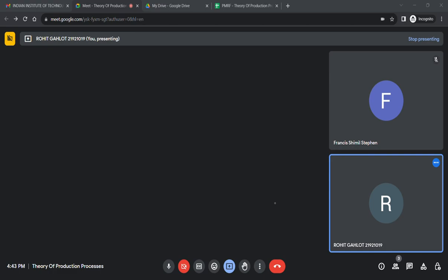So here, can we use that d by 6? Actually, we cannot use d by 6 directly for the riser here, since the height is not given equal to d. But we will have to assume that. You can assume h is equal to d, or h is equal to d by 2, as per your convenience, because it is not given. Without that, it won't be coming. So generally it is assumed h is equal to d.